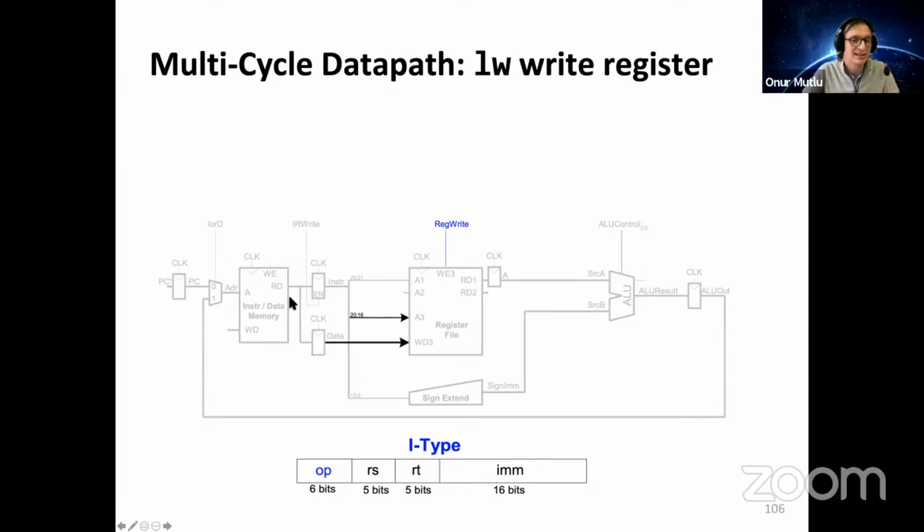In the next clock cycle of execution, we take the data that was output from memory and latched, and write it into the destination register as specified by the instruction that's still sitting in the instruction register. Remember, we're not clobbering this instruction register because we fetch the instruction over multiple cycles, we do stuff, but that instruction register doesn't get updated because we didn't fetch any new instruction. Okay, so we use the same control signals, the value that's in the instruction register to determine the destination register. And whether we need to write to a register right over here also, okay?